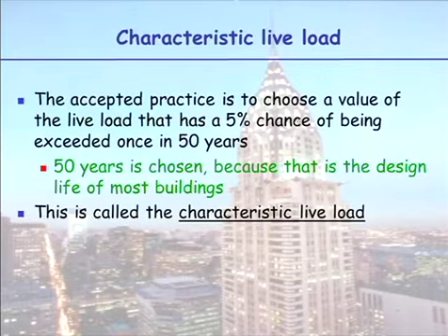In terms of the live load, particularly with people loading, in the week of a building, you don't expect loads to be high. But in the year of a building, you may say, well, every year in this building, there's the big Christmas gala, and on that Christmas gala, we get hundreds of people in this building. So depending on what time period you're looking at in the life of a building, you may have heard most buildings have a 50-year design life. Okay? They're now slowly increasing that. I think one of the bridges in Brisbane has just been built for a 100-year design life. So the accepted practice is to choose a value of the live load that has a 5% chance of being exceeded once in 50 years.